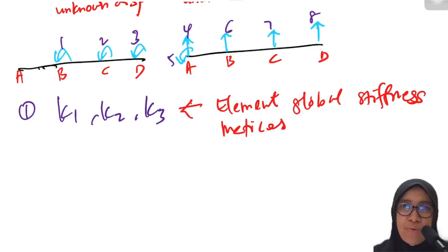For a beam you don't need to put the arrow or the coordinate, because a beam has the same local and global coordinate system, and the direction is always going to the right side. So we don't have to calculate CX and CY as well. Besides K1, K2, K3, this is actually the compulsory step, because from this we will establish the structure stiffness matrix.